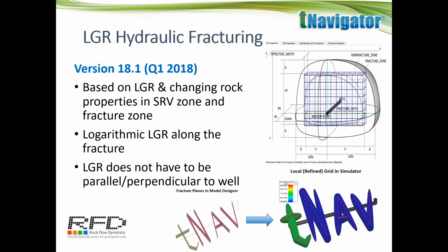Starting with the LGR hydraulic fracturing, in the beginning of 2018, we introduced the hydraulic fracture model based on grid refinements and changing of the rock properties in the fracture zone, as well as the stimulated rock volume zones, SRV. Such an approach allows you to define fractures of any shape. Your LGR does not have to be parallel or perpendicular to the well. We also allow the logarithmic LGR along the fracture and permeability modification in the stimulated rock volume zones.